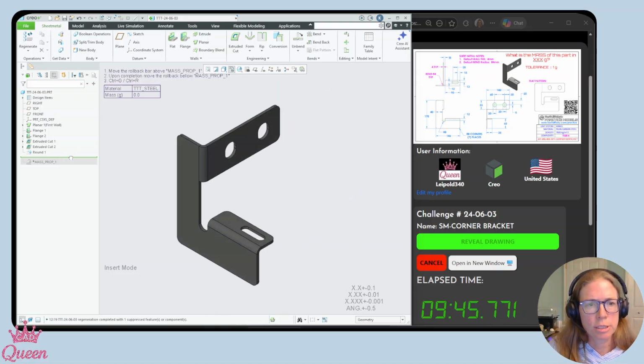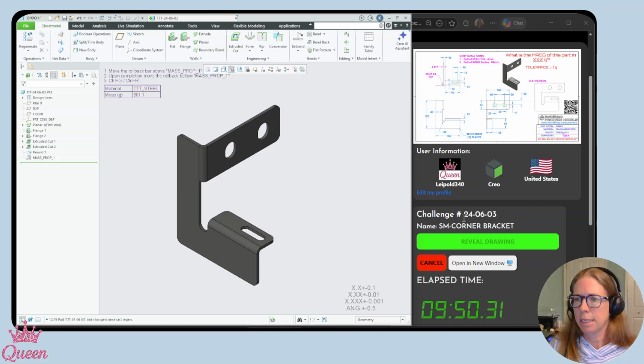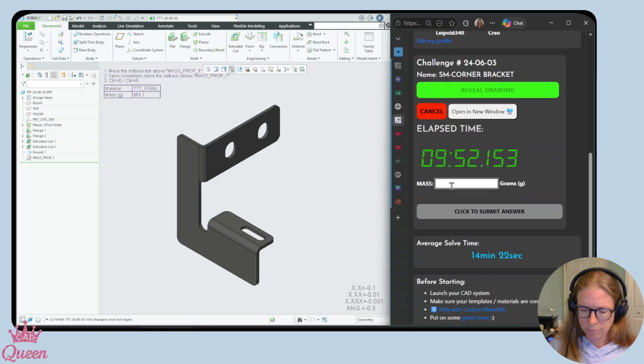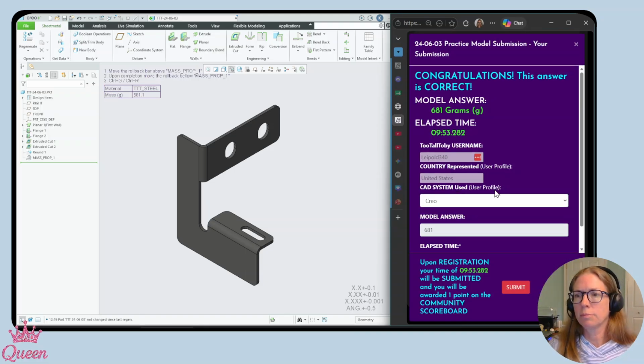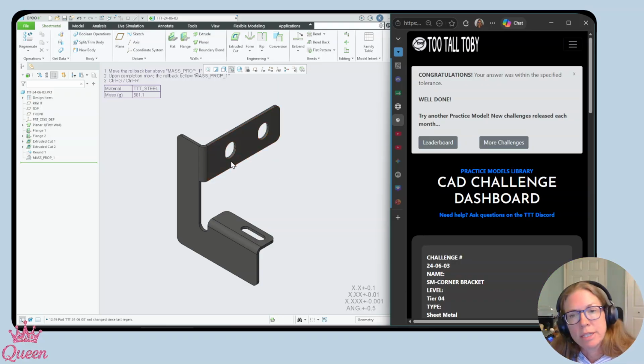So what we're going to do is check our mass. It was 681. Beautiful. All right. So just a quick review there. Some of the things we like to use, the slot tool clear or the rounded racetrack from the pallet tool. Here we used copy and paste. We used a 3-tangent circle to get the arc cut out. Paid careful attention to which way our flange was going.